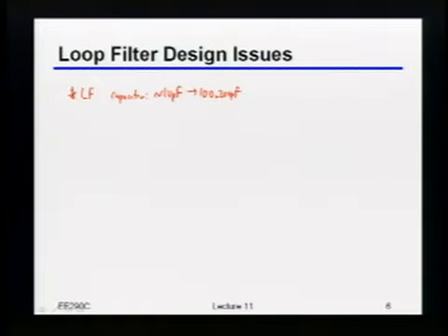Okay? So how are you going to want to build that capacitor? Like physically, how are you going to want to implement it? MOM cap. MOM caps. Okay, so you said MOM cap. You could do a MOM cap, and in fact, as we'll talk about in a second, you may actually have to do that, but that's going to take some space, right? And by the way, I won't be able to route anything anywhere for the entire block of that MOM cap, right? So how else do you think you might want to do it? MOS cap. Yeah, MOS cap.